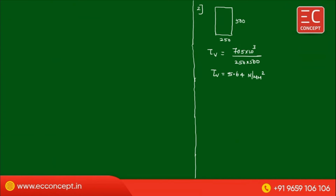For example, let us take M25 concrete. For M25 FCK, what is tau C max? Tau C max for M25 concrete is 3.1 megapascal, that means 3.1 Newton per millimeter square. That is your answer. Now in this case, tau V is greater than tau C max.